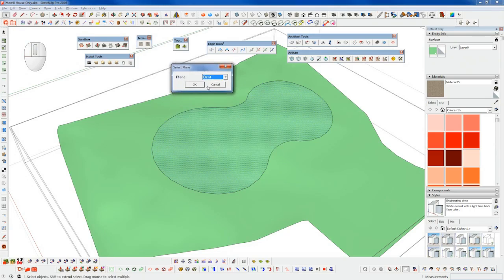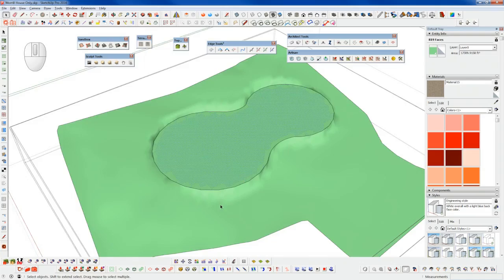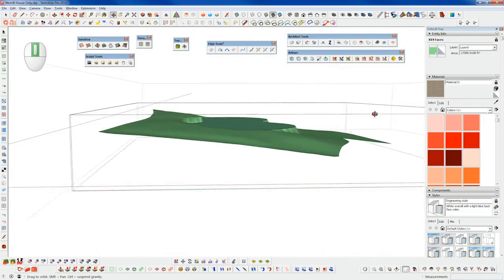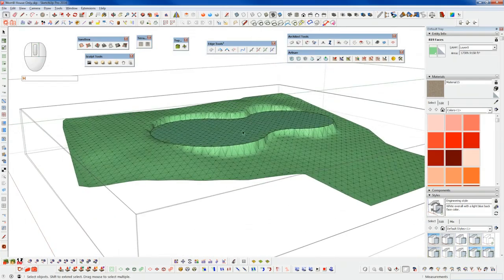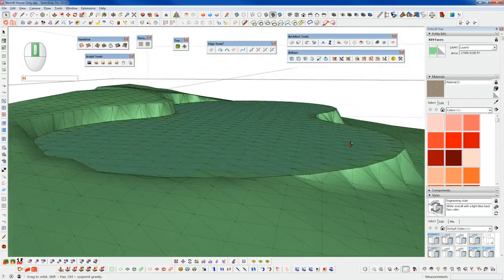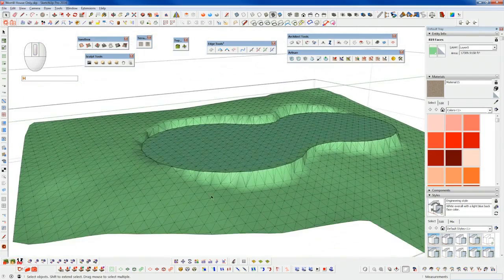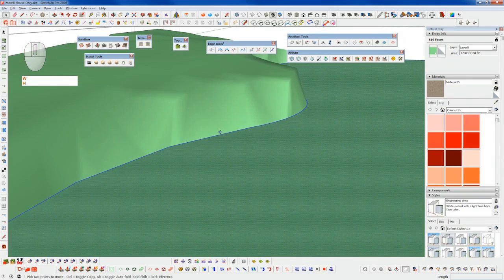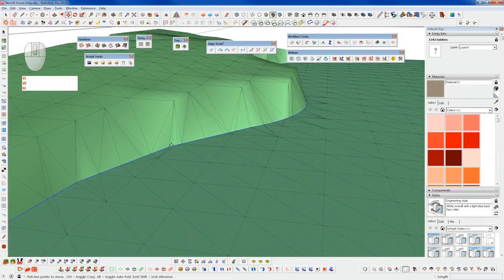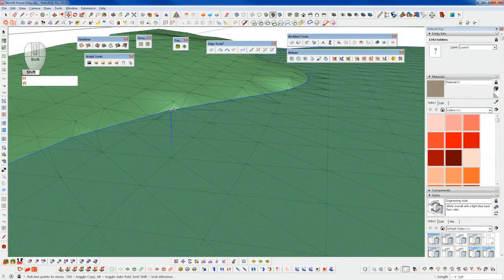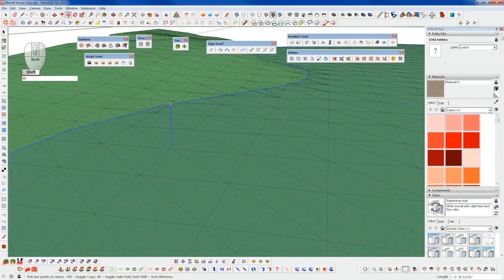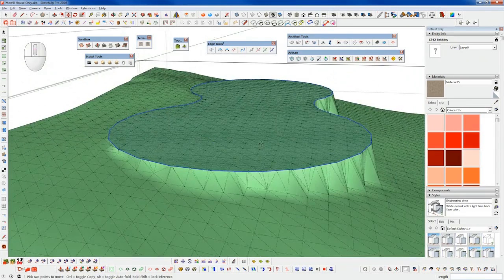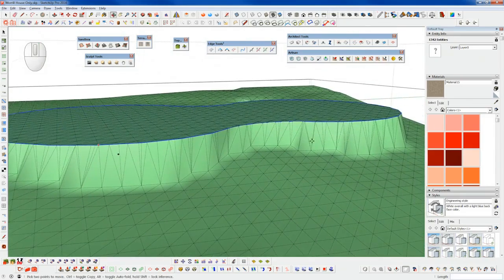And what I can do is go in with the Make Planar option of Artisan, and I'm going to set this to XY. And we can see what happened there, that because we have a nice clean quad mesh, we're able to make that planar. I can even grab this interior here and lift this up on the blue axis until that's almost level there.